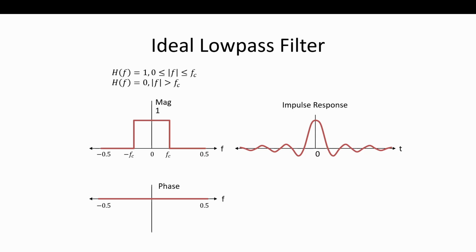This is your idea of a filter design, and we often want this approach to get to what we get closest to this mythical brick wall filter, right? The brick wall filter that's not realizable, but there it is in frequency. I'm showing a filter that is going to reject everything above a cutoff. It's going to pass everything without any distortion within its passband. And it has zero phase. So you know what that means when a filter has zero phase? Because we do implement zero phase filters in post-processing. So it's a good takeaway. Anyone know what a zero phase filter is?